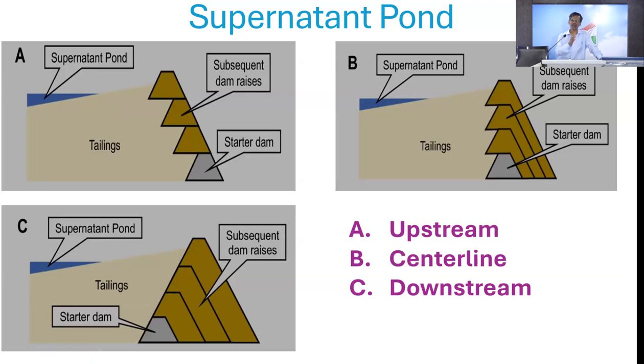In case of red mud, it is toxic also. So that aspect needs a treatment. Suppose it is chromium, the most. They have a treatment plant all the time near the chromite mines. Without that treatment, they cannot allow any water to go outside. So this method of treatment of the liquid should also be kept in mind when we are going for this type of tailing design.